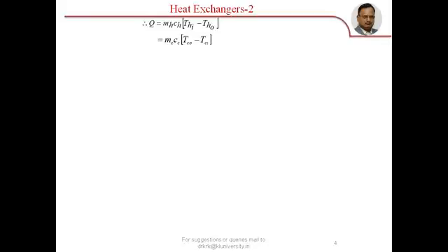So across the hot fluid and cold fluid, another equation is developed, which we have seen in the fundamental chapter on combined conduction and convective transfer, depending on the overall heat transfer coefficient. So Q is equal to UA LMTD. The earlier topic centered around three equations. One is Q equal to MH CH (THI minus THO), and the other one is MC CC (TCO minus TCI).